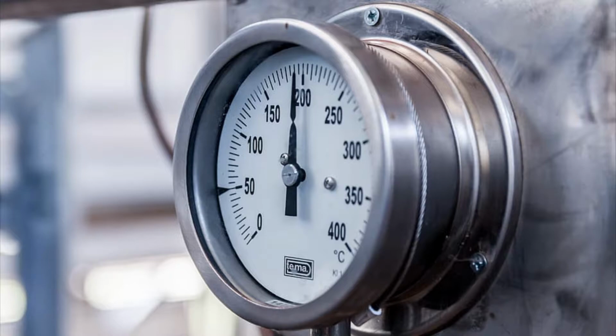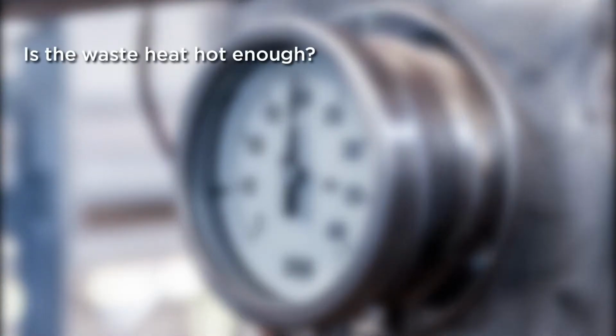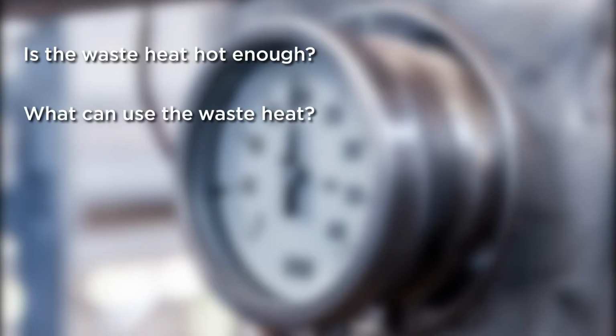Therefore, it is best to start by identifying any processes which produce waste heat and ask yourself the following questions. Is the temperature of the waste heat hot enough to be useful? Some waste heat may not be. Typically, waste heat should have a temperature differential of at least 200 degrees Fahrenheit between the two processes to be useful.